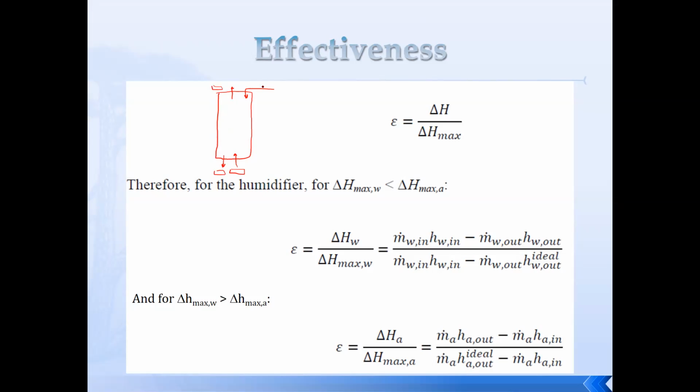And we call it the enthalpy pinch. What we are doing here is calculating it, assuming that the enthalpy pinch is occurring at the inlet and the exit. These definitions are written based on the conditions at the inlet and conditions at the exit of the unit. In reality, the enthalpy differences can get closer within the unit. And this is something that we cannot do at the moment because we are doing just a control volume analysis.